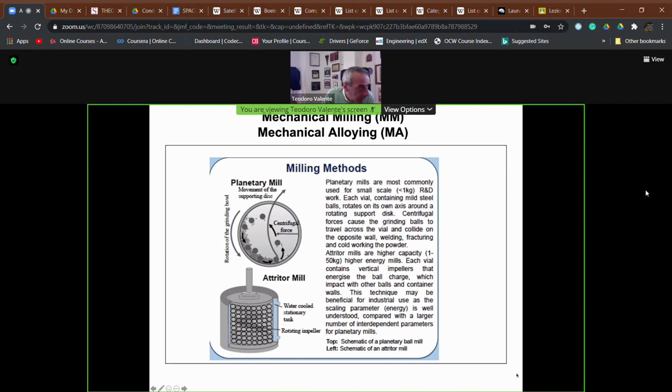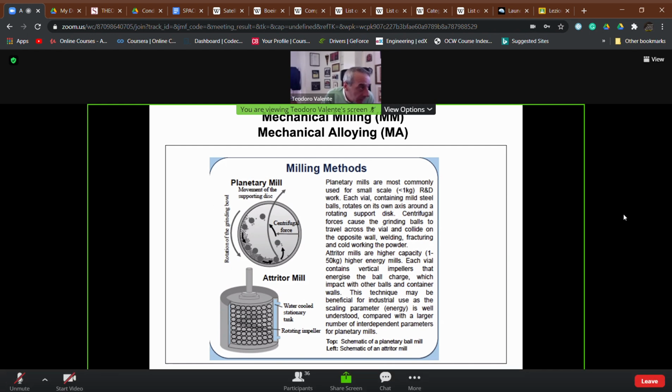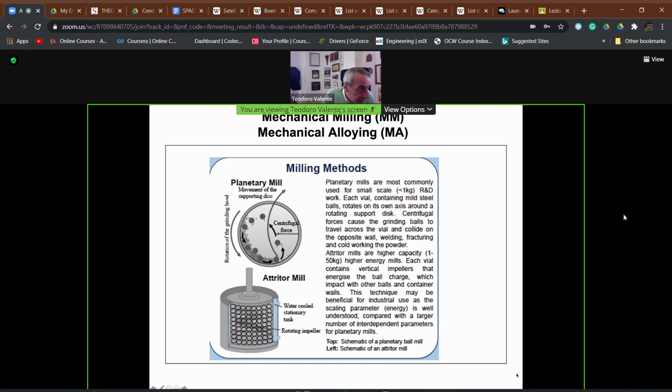The second aim is to dissolve one material or compound in another one, depending on the starting materials, in order to have a solid solution. Thus, the final result of this pre-step is the fabrication of powders having a suitable granulometry distribution, that is a suitable average diameter, and being composed of at least two different materials, that is an alloy.